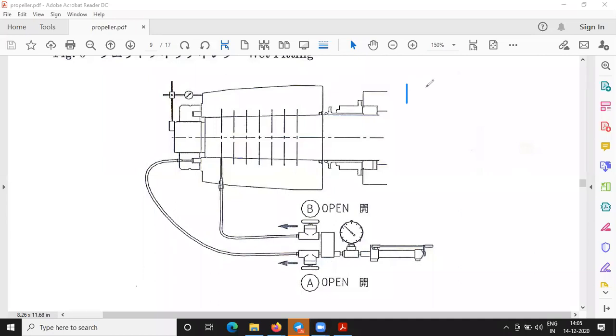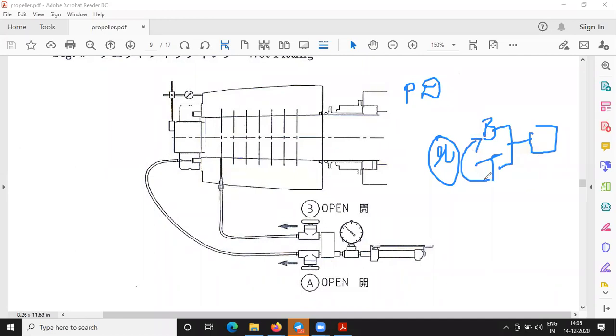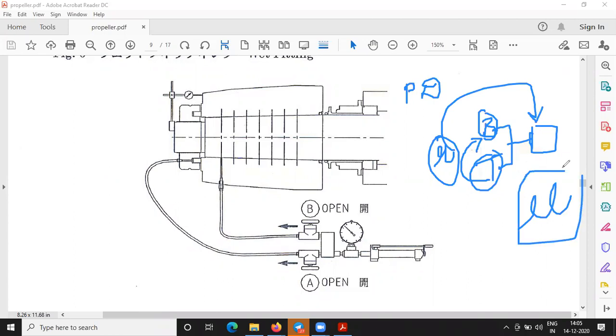The actual push-up distance is nothing but the actual friction that you want to have in between the propeller boss as well as the tail shaft. So the only friction is the reason why the torque from the tail shaft is being transferred to the propeller. We are talking about the push-up distance, we are talking about the pressure, but what is the ultimate point that we want to reach? That is mu, the friction between the boss and the shaft. So followed, everybody?